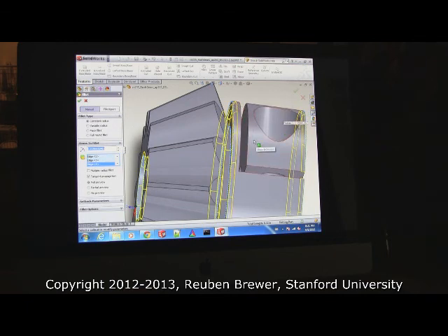Okay? Now I'm going to show you how to do a face. Just so you know, doing fillets on faces, very tricky business. Be careful. Select this face right here. See how it did multiple edges? Now select this face here, right here. Yeah, if all of the lines turn blue and the yellow goes away, it means you can't do that face. And that's okay, that happens a lot. So if that happens, just don't do that face. You only clicked one face right now, right? Yeah, this one right here. Now click this face, right here where my mouse is. And that's the only fillets that we're doing.